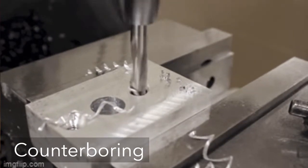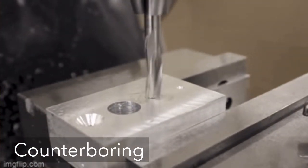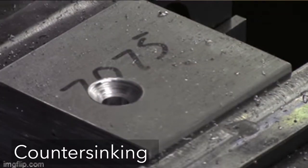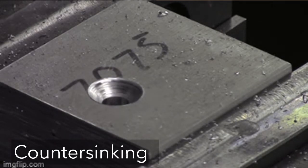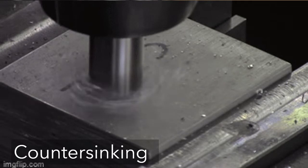Counterboring provides a stepped hole in which a larger diameter follows a smaller diameter partially into the hole. Countersinking is similar to counterboring, except that the stepped hole is cone shaped for a flat head screw or bolt.